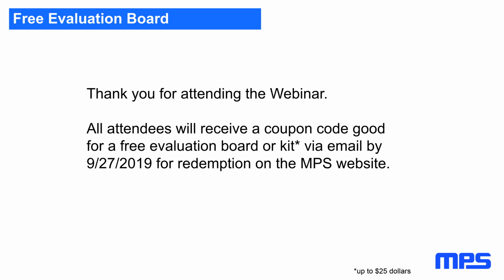So typically on a good board, I make a fence of vias around the outside, so that no corner is really radiating. There are typically no other limitations on vias that you could use, and vias in parallel get inductance down. So if you connect planes or something, more vias are always better. They cost a little bit, but that's typically not a concern.